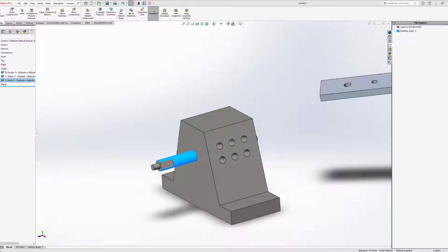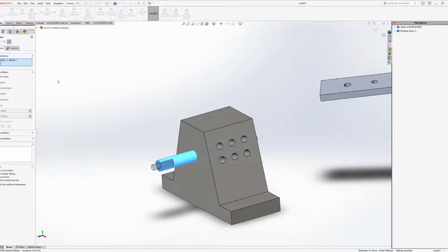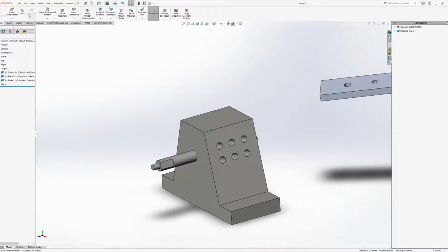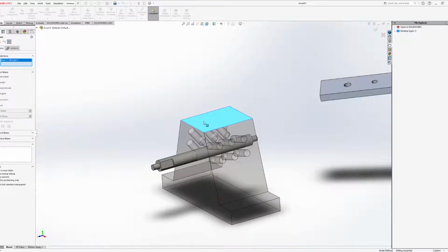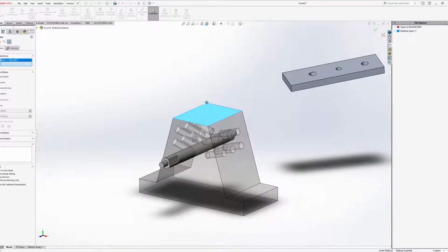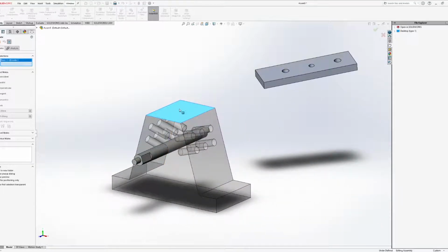So another thing to note that is on the PowerPoint, but I'll just explain it here. Usually when you click on certain surfaces, SolidWorks and the mate assembly will typically recognize what mates are going to be allowed. Maybe you noticed it, maybe you didn't, but I clicked on the top face of this guide, and you can see I can't choose a concentric mate anymore. Well, why is that? If we're thinking about what concentric means, it means that we have two circles that have an identical center, or rather they start at the exact same center.